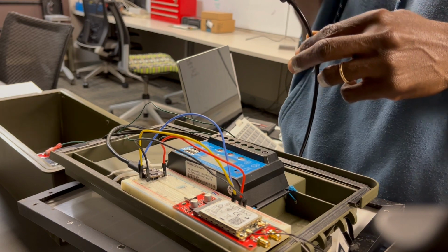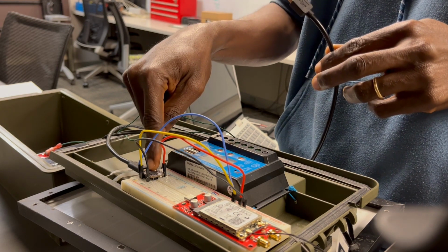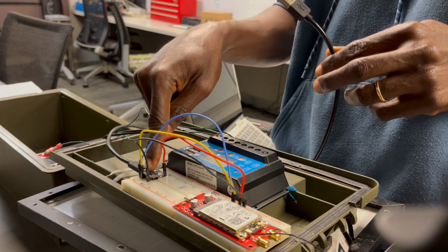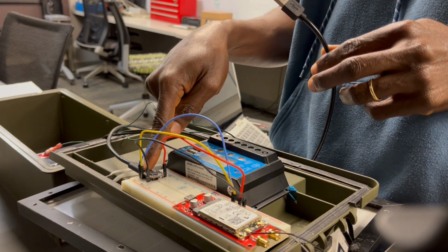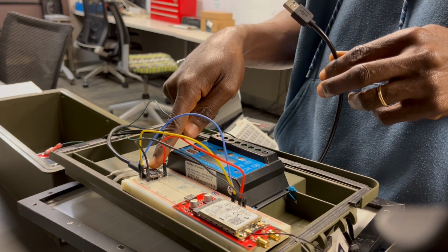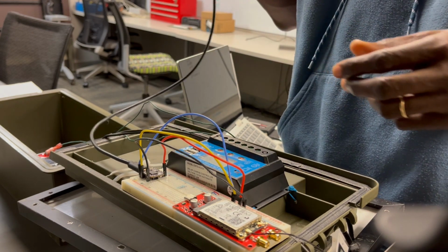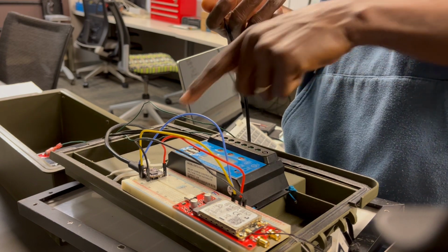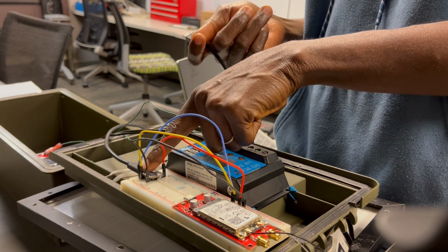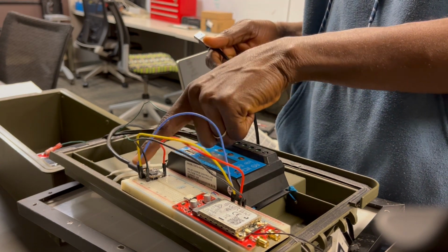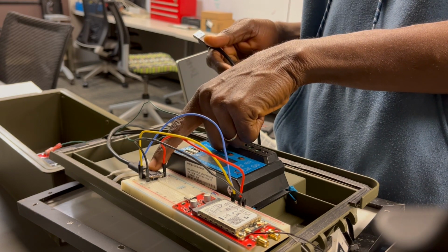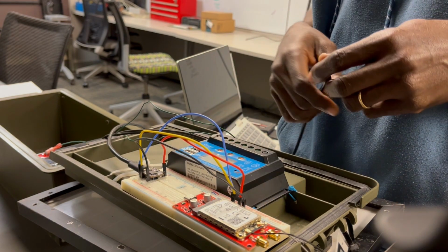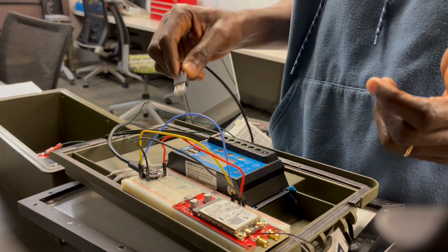And then, from the wireless access point, I build a web server on the QT-PY, so that anytime I connect, I don't need to use the USB anymore. Just with the Wi-Fi on my phone, I connect to the IP address of the QT-PY and I will be able to send serial commands through the QT-PY to the Swarm board. So that's the goal of this.